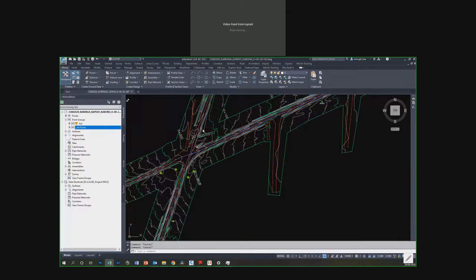See, for designing, if you say to your surveyor that this is your preliminary requirement and this is the data set, what you need is a cleaned up base plan which shows only the line work and the physical parameters, whatever is there. Then you need a point file which gives you information about the XYZ of that particular location and the description of it. These are the only two things which you need from the surveyor. Rest of the things you need to create. I'm just waiting for Civil 3D to do the exporting part.